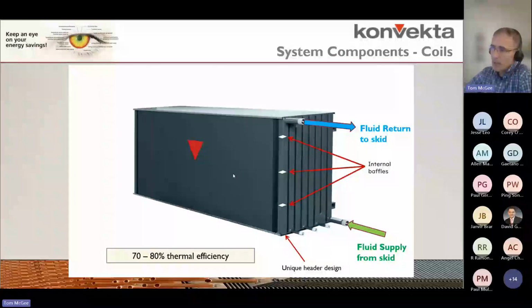Because of the way this is circuited, as we saw in that previous slide, the one thing you do have to remember is in order to fully drain the coil, you've got to open all drain valves that are associated with a coil section.